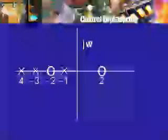Alright. Now we can proceed in two different ways. This characteristic polynomial, I can write down explicitly what it is. So I will do it for our example, and you will see that the situation becomes more complicated if you have a larger number of poles and zeros. I had (s+1)(s+3)(s+4) + k(s+2)(s-2). That is the characteristic polynomial. Let us call it p(s), and we are trying to solve the equation or find the roots of the equation p(s) = 0. They are the points on the root locus, the complex numbers s on the root locus, right? Now let's look at this. Now you expand this out and you expand this out. Alright. So if I do that, I'll get what?